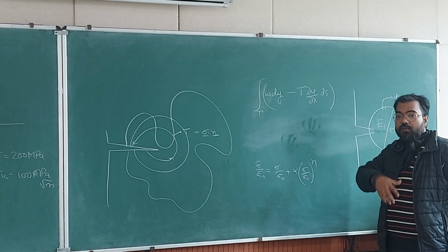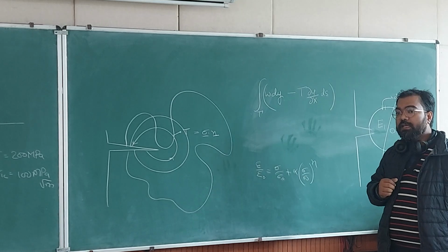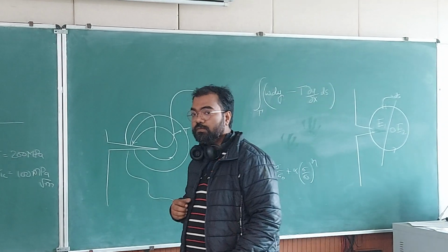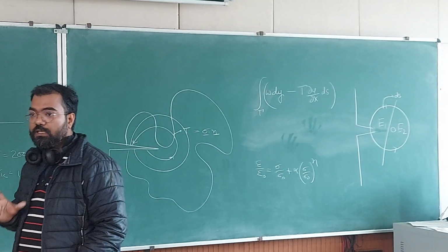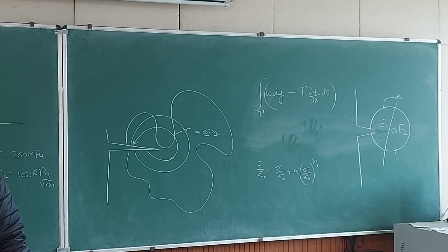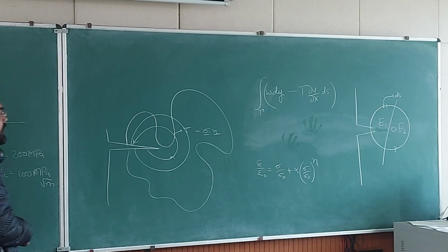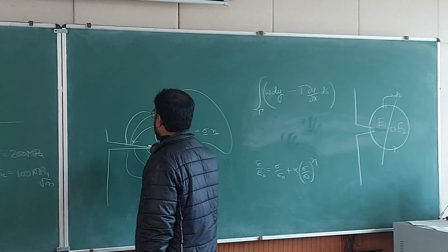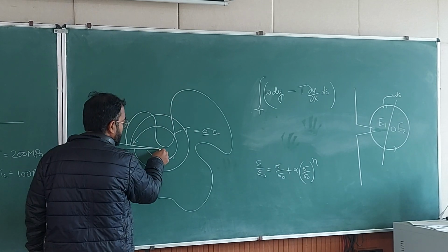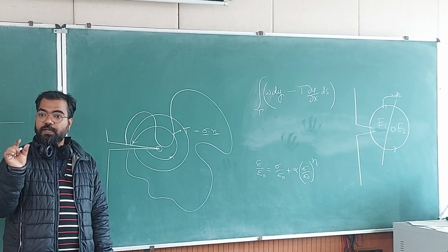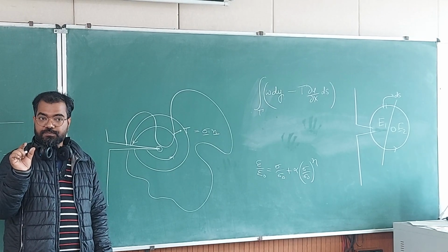Okay? So assume that if the crack is not growing, it is not going to change its property of changes in the energy, whatever is happening. So this line integral, if you calculate along a contour which encompasses a crack tip, is going to give you a particular finite value.